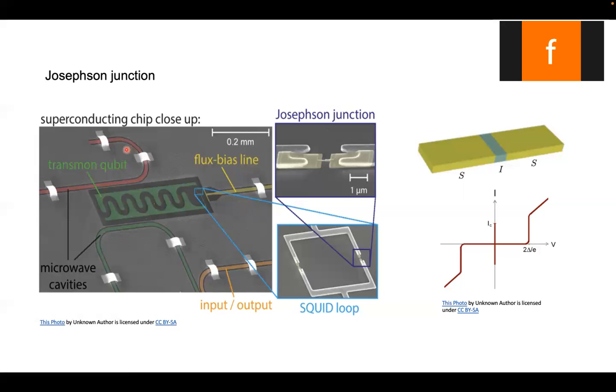But you see, then here you have this line, and this is a microwave resonator, which is coupled to this device here. Because this is a metal, and between them you have an insulator, essentially you have capacitive coupling here. The electromagnetic field makes the connection with this coplanar waveguide resonator. This is typically for doing some measurements that I will explain later.